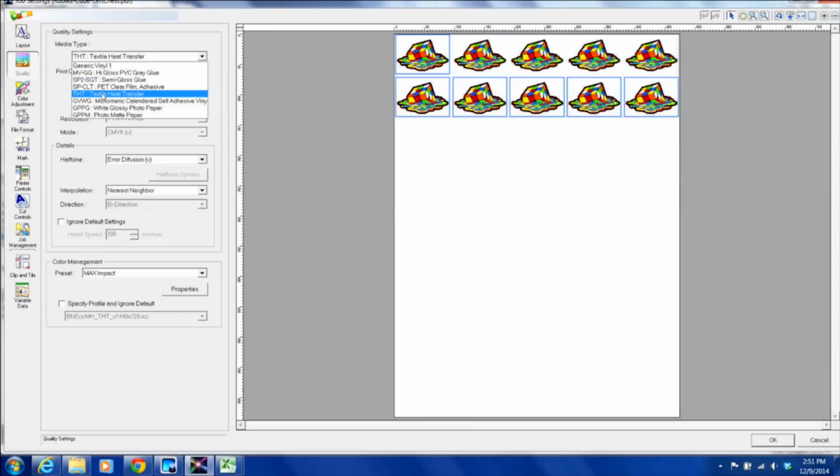Here we have our print quality. So you can print standard, draft, or draft 2 on the BN20, and this gives you an idea of how long the print time is going to take on the right hand side. So draft, as you can see, the resolution is 1440 by 720 dpi. That is actually more than enough resolution. You won't see any image loss. If you went to draft 2, you would probably start to see a difference, but the draft and the standard printing at 1440 by 1080 versus 1440 by 720, there is minimal difference, especially when you're dealing with vector graphics and printing onto heat transfer material. So you tell it the print quality that you want. It gives you an estimate of how long it's going to take to print.